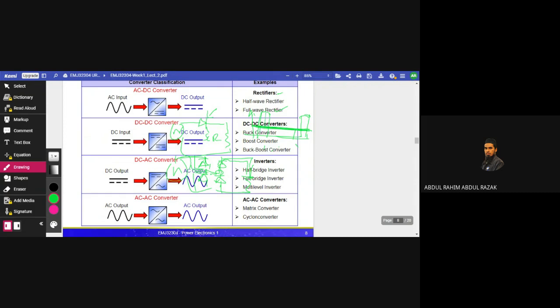The slimmer the pulses, the lower the voltage you can apply. You can adjust the voltage to a lower level, but you cannot supply more than the maximum. You can reduce it accordingly, based on the kind of pulses and duration of pulses that you apply to the switch. So that's how the DC-DC converter works.